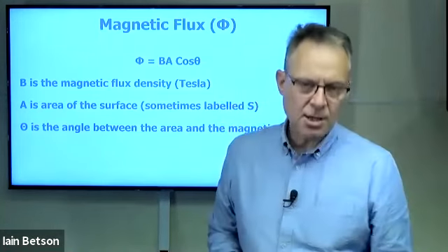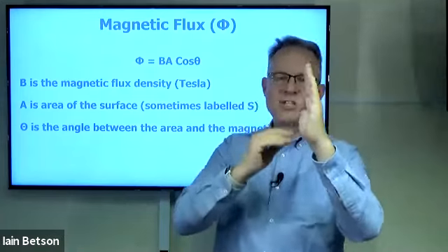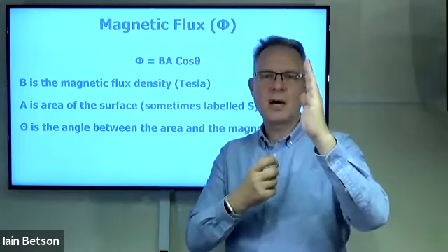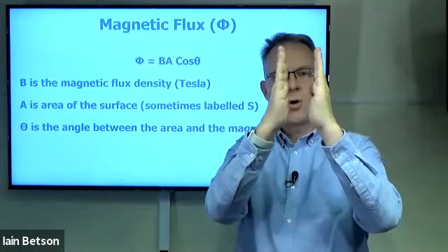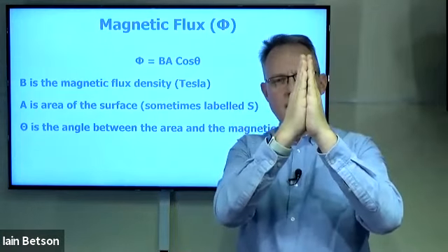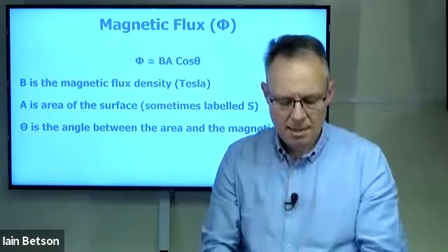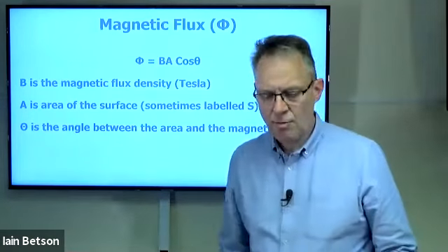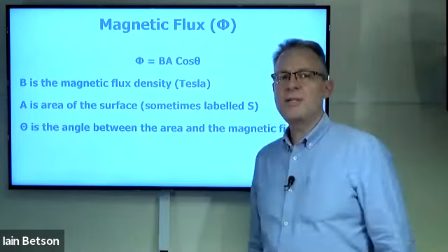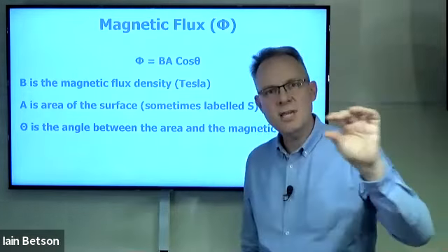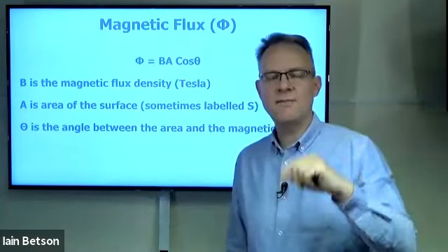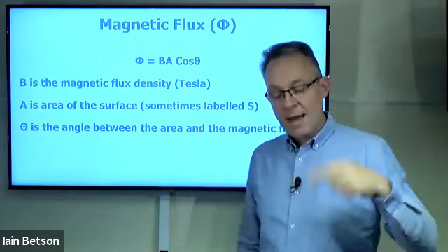Or if the head is at a different angle, perhaps the wrap or the zenith, and these are other terms that I covered in webinar 1 on lineup, is not correct, and the head is not perpendicular and correctly surfaced against the tape. If it's not correctly surfaced, the angle between the area of the tape that's being magnetized and the magnetic field from the head will vary. And that is why if you get